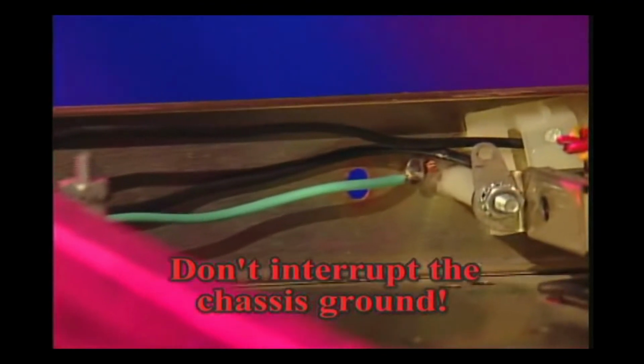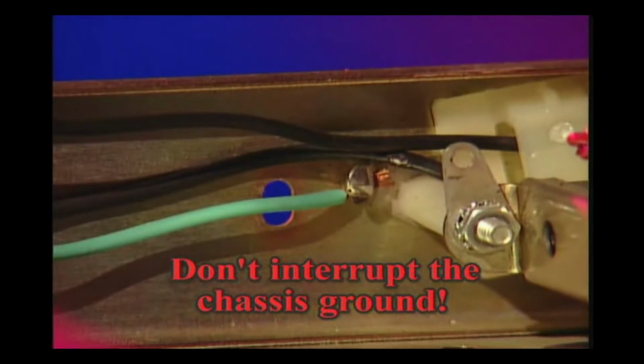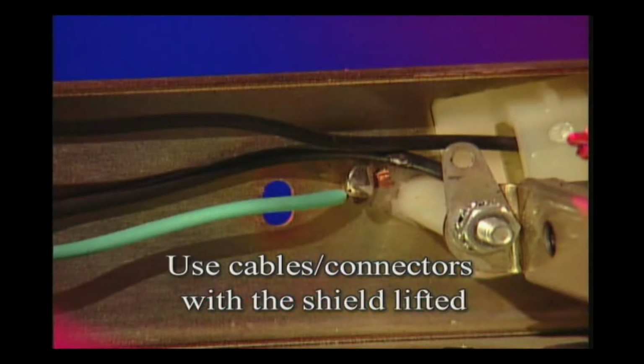You don't interrupt the chassis ground. That would make the device ungrounded and a shock hazard. Instead, we use modified cables and connectors with the shield already lifted in certain places in the system.